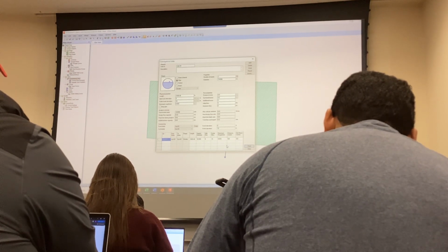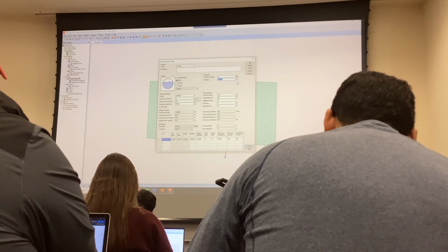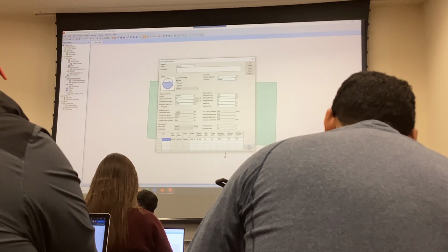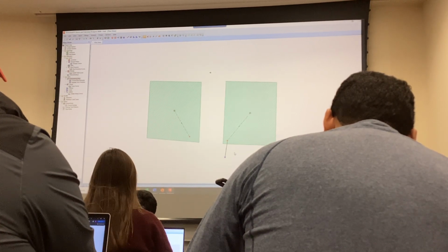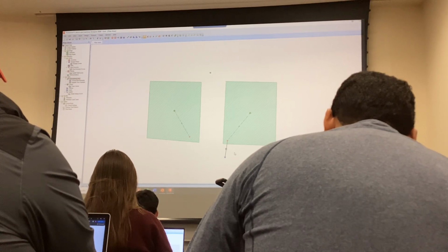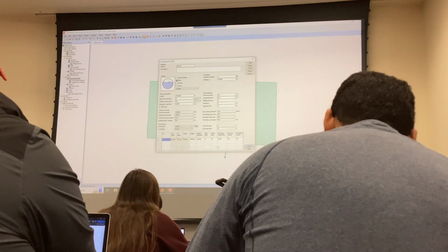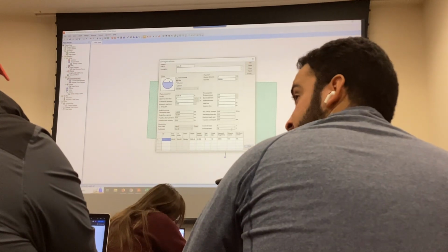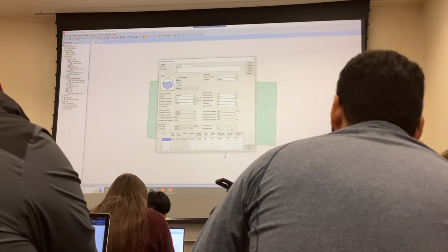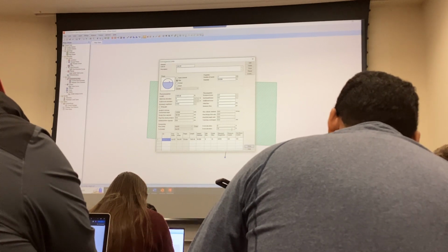So let's say hypothetically, just to avoid having issues, I'm going to put a huge pipe going into my detention. I know this is ridiculous, right? So you're going to put this pipe into your detention, and what did I say about the elevation? If your pipe enters your detention, it cannot enter below the invert of your detention.